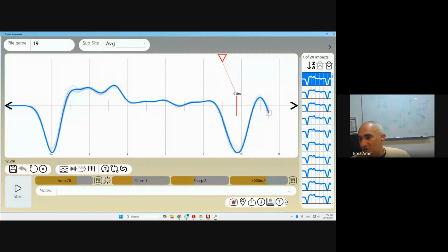Yeah. Okay. So the question is if this indicates an increased cross section in the point of the pile. Well, theoretically, yes. But if you look at this, it's really minor, and you should just ignore it. We're looking for bigger features, things like that. That's a typical feature of the pile. Interpreting that would probably, in most cases, be over-interpretation. We're going to look at this in a while. We can try to put this into signal matching and see that it's not really going to give us anything dramatic in this area.